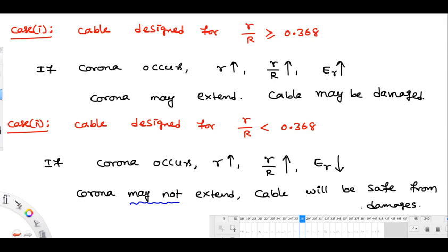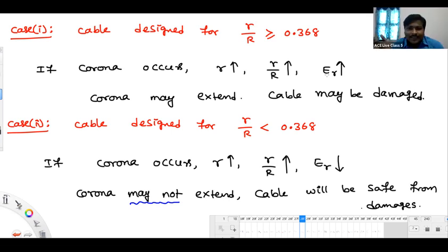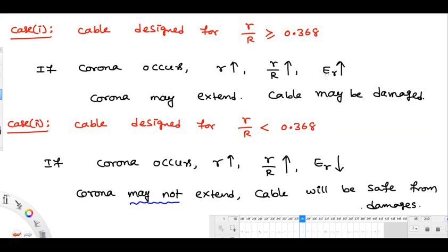Another point of view: the voltage drop across the capacitor will be more for a long transmission, na? It won't be used for a long distance in case of AC, right? You are talking about cable. For AC, we'll discuss length variation in the cable later. We don't use it for longer lengths. Why is it so? High charging current is one reason.